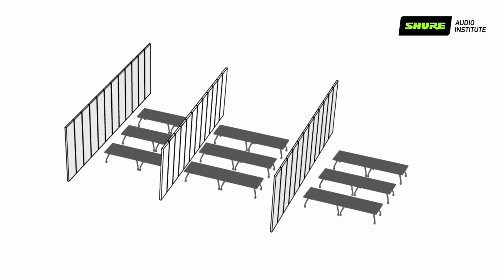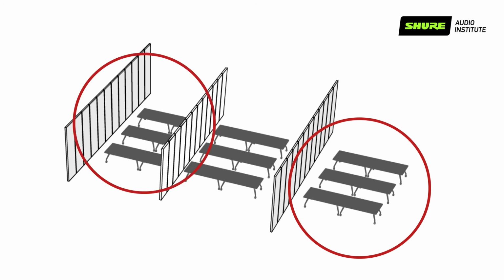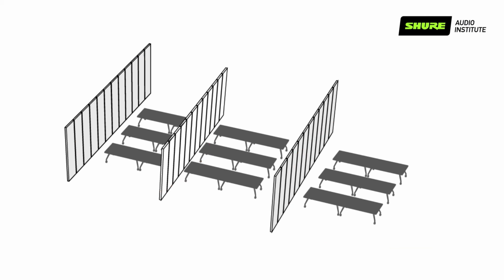Another scenario is in a hotel ballroom where multiple areas are side by side, potentially interacting with one another. But at opposite ends of the divided space, the individual rooms are far enough apart to be considered separate RF zones. Taking that a step further, if there's a roaming transmitter that will need to be used in any of the RF zones, it can be considered its own zone that interacts with each of the others.